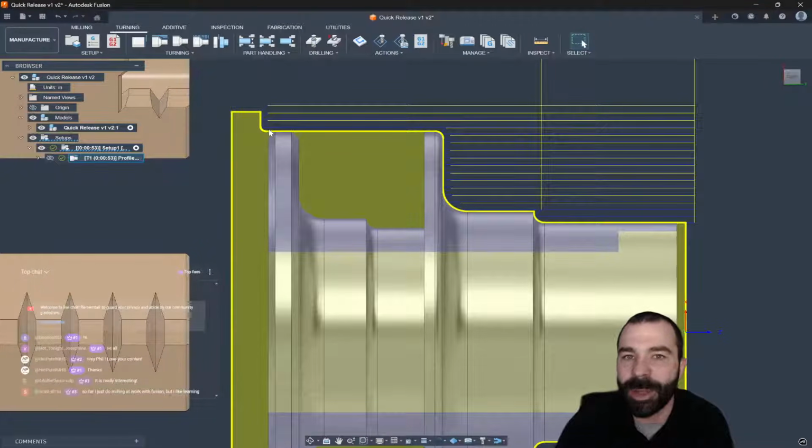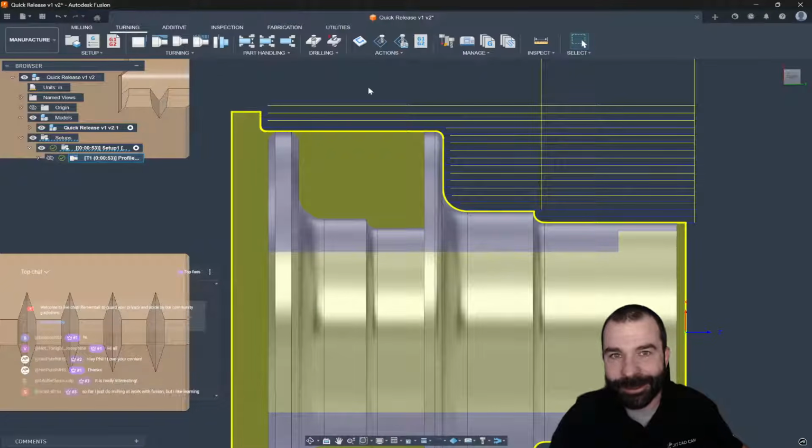And just like that, I'm also using things like tangential extension to go past my part without grooving in, as it would be referred to, or undercutting or waterfalling. So Scott out in chat, you just do milling at work with Fusion, but you like learning. Scott, we appreciate it. Now you've got to go convince your employer to buy a lathe, right?